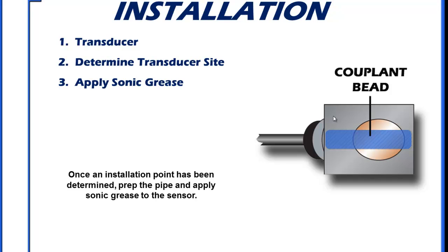And you do need to take care that you put enough grease on the transducer, wipe off the pipe, and then re-insulate the pipe so you don't have a rainforest inside the pipe that washes away the transducer grease. So in that case, as long as you seal up the installation and the pipe doesn't sweat, you're good to go. The silicone grease pretty much stays there. So toothpaste on a toothbrush for the most part as far as your grease on the pipe.